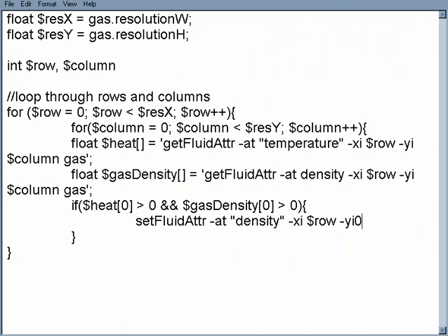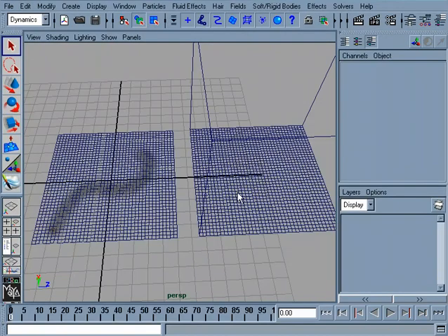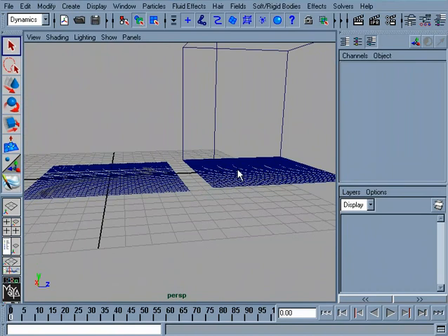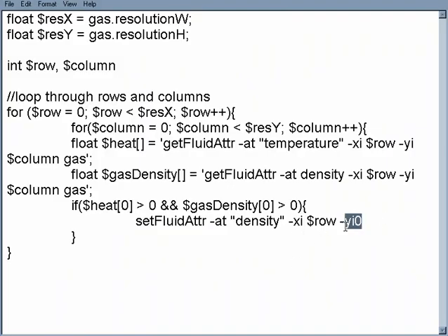Okay, I'm going to set the Y index to 0 so that I can make sure that it actually ignites at the bottom of this 3D container. When the fire actually comes up, it'll ignite at the bottom of this Y-axis. In other words, 0. So we'll make the Y-index 0.